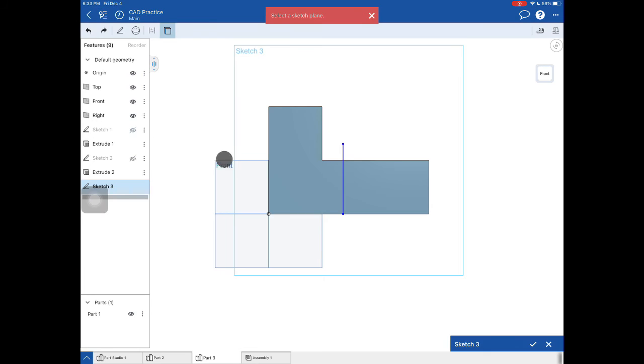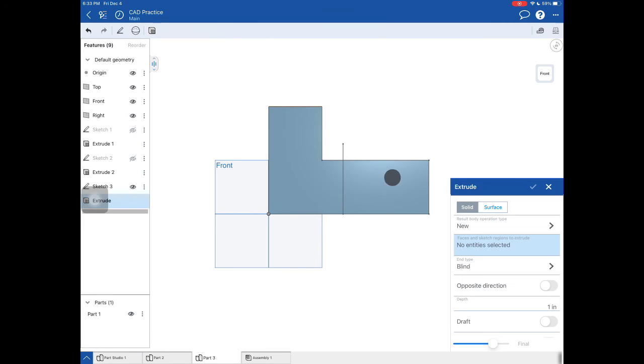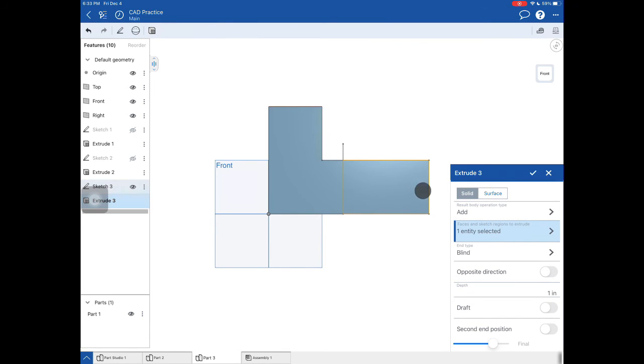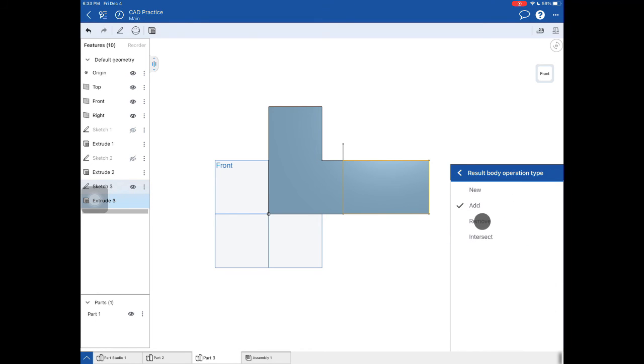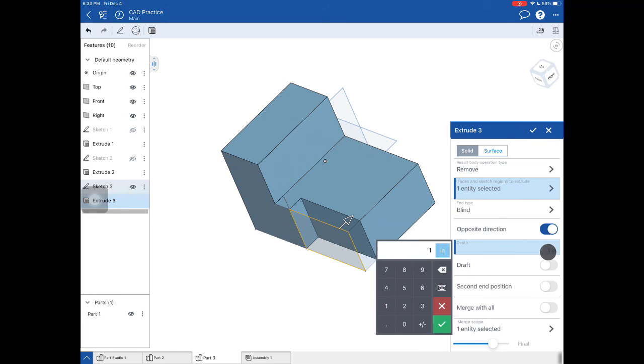I'm going to find the feature use, which allows me to use the already existing object lines in my next step. I can then hit the extrude option and cut or extrude or join, whatever process you want to do to that piece that I selected.